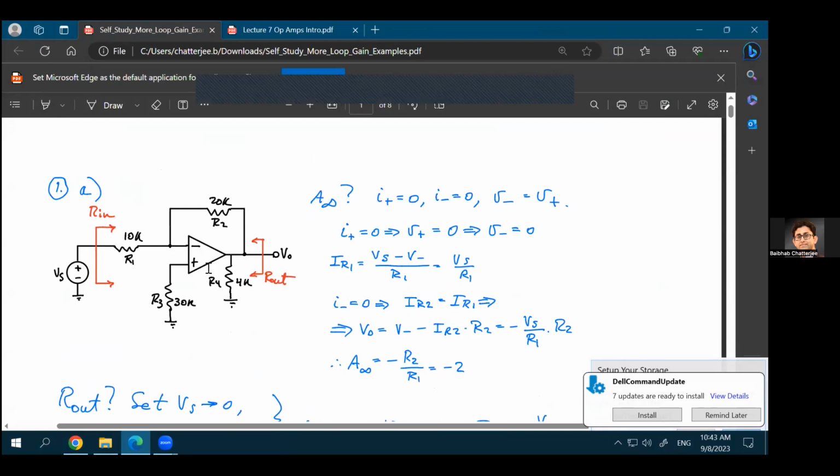So as you see, in this first one, you have an op-amp, you have some kind of a configuration over here where you are applying this input to the inverting terminal of the op-amp. As you know, the op-amp will basically have a non-inverting terminal, an inverting terminal and an output. So it's a 3-terminal device. And the output is basically the gain times the difference between the positive terminal and the negative terminal. That's what the output of an op-amp is in an open loop scenario, right?